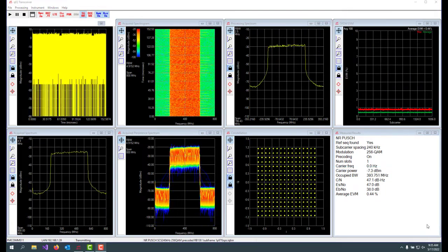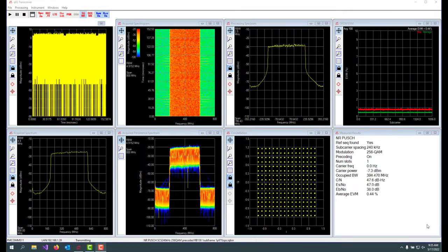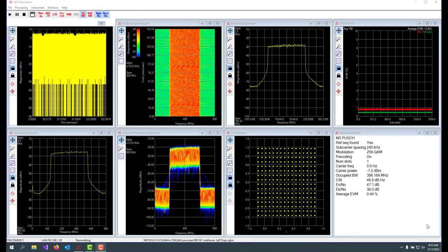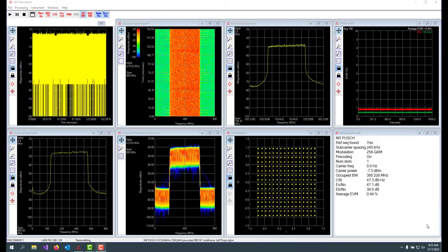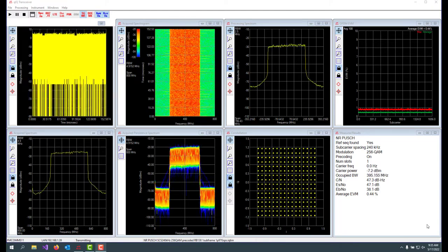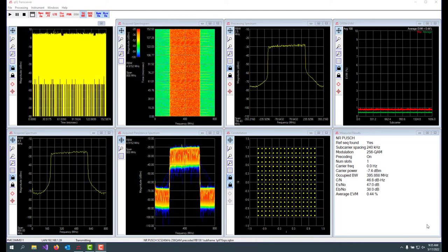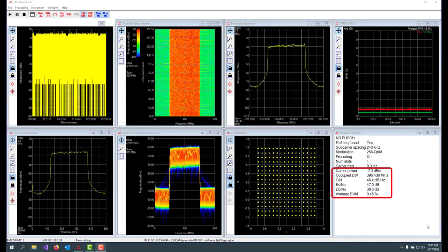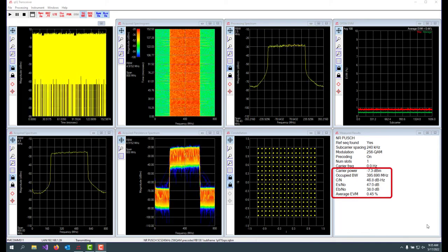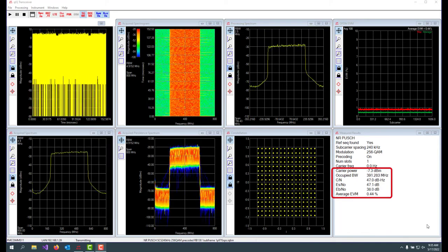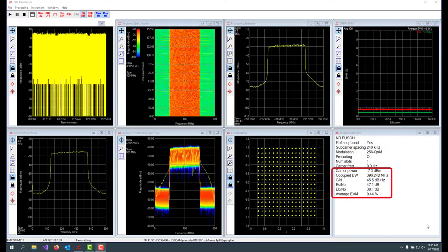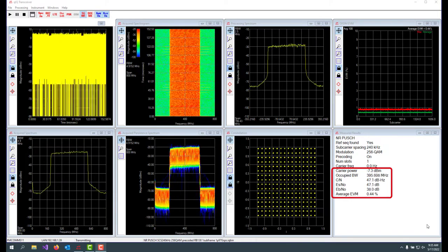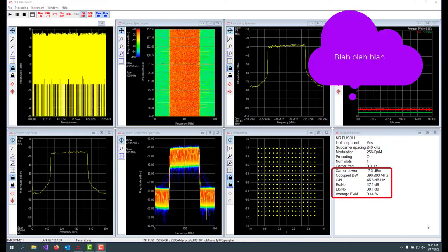Let's push the system a bit more. Let's use a signal with 240 kHz subcarrier spacing, 138 resource blocks, which is the maximum, and use 256 QAM modulation. When we run this signal, we get an EVM around 0.45% and an ESNO of about 47 dB. For an occupied bandwidth of nearly 400 MHz, those are quite good numbers.